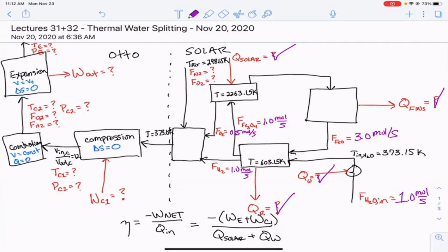And if you remember when we talked about this earlier, the whole thing that we're trying to do here is that if you were to let a very, very hot gas enter the compressor, that compression would go to an extremely high temperature, then the combustion would be even hotter. So we have to cool this down a little bit before we start to burn the hydrogen that we just made. And the way that we wanted to do that was to just mix in air such that the temperature leaving this box is 100 degrees C.